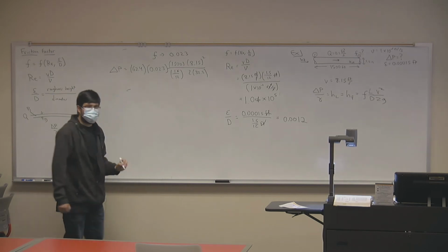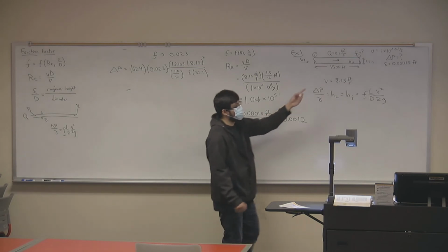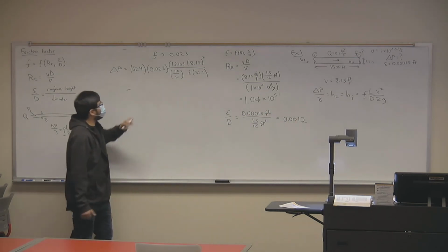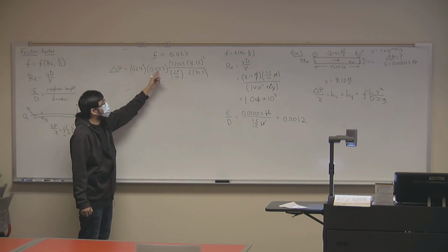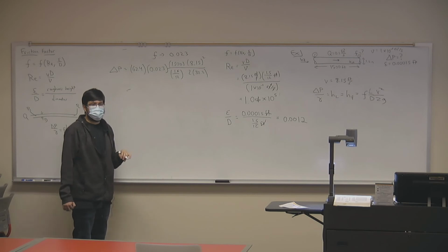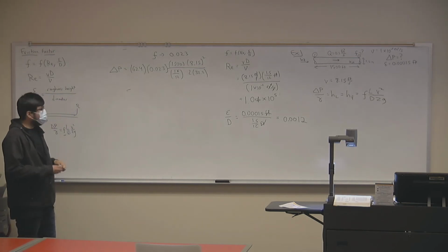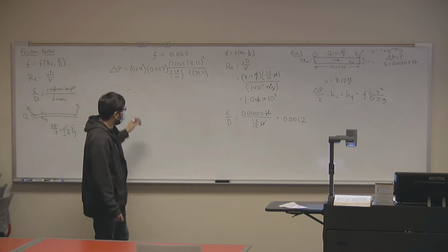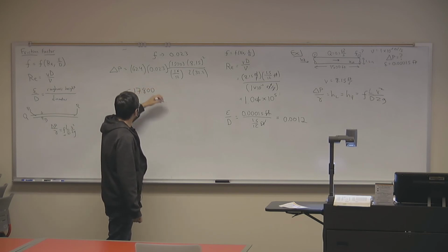And what is that pressure drop equal to? Well, it can be different because I had a different friction factor. I just want to know what the difference is out of curiosity, because we only have a difference of 0.003, right? So what's that pressure drop equal to? Got it. 17,763. How much is that in PSI, divided by 144? 123.36.